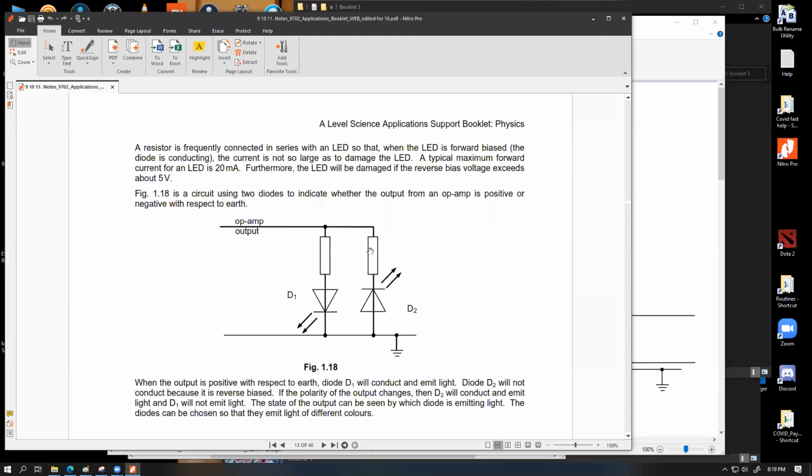The reason we have the resistors connected over here, which is pretty important, is for the safekeeping of the diodes. Because you should understand, ideally diodes are supposed to have zero resistance in forward bias, which means whenever this positive supply is, let's say in a certain scenario, the output of the op amp is positive, then in that case current flow will happen through this diode. Now, being an ideal diode, or LED, a light emitting diode, even if you consider this as an ideal diode, it will have zero resistance, which means it can essentially allow a very large amount of current. We don't want that to happen. So for the safety of this LED, we are introducing a small resistor over here, which will limit the current value, but the diode can still glow for whatever current flows through it.